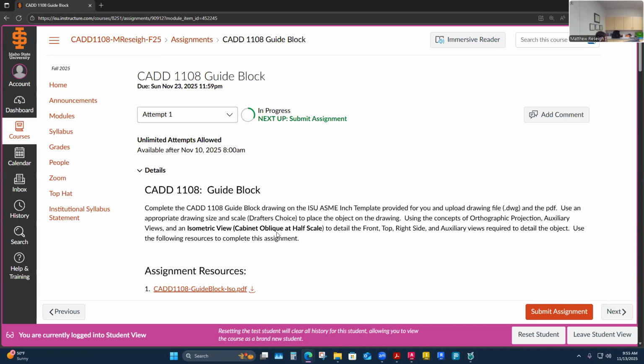On page 511, your book shows the three different obliques. The cabinet oblique is the middle one that we discussed. The first one is the cavalier oblique. It also uses a 45-degree projection angle, but it's drawn at full scale. The two images show the same object, one drawn at full scale, one drawn at half. You can see that difference.